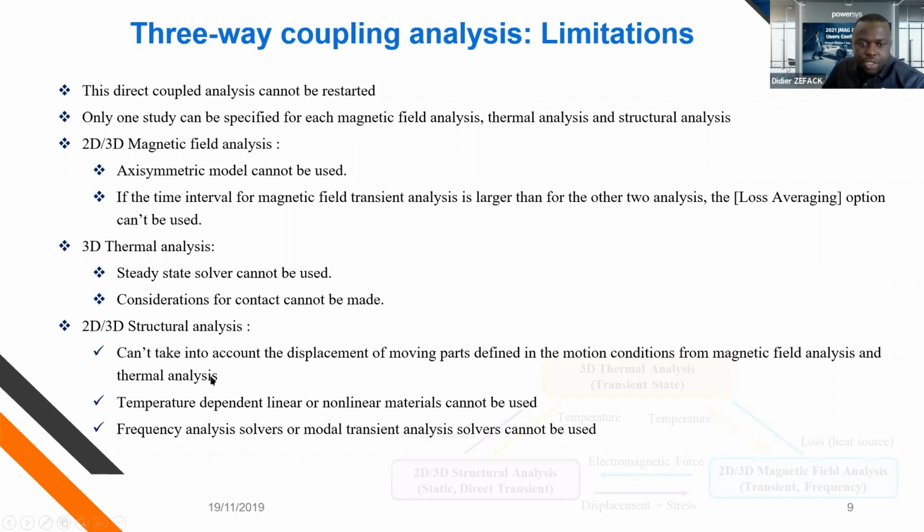And also materials whose properties depend on the temperature, linearly or non-linearly, cannot be used. The structural analysis cannot be run with the frequency solver or modal transient solver.